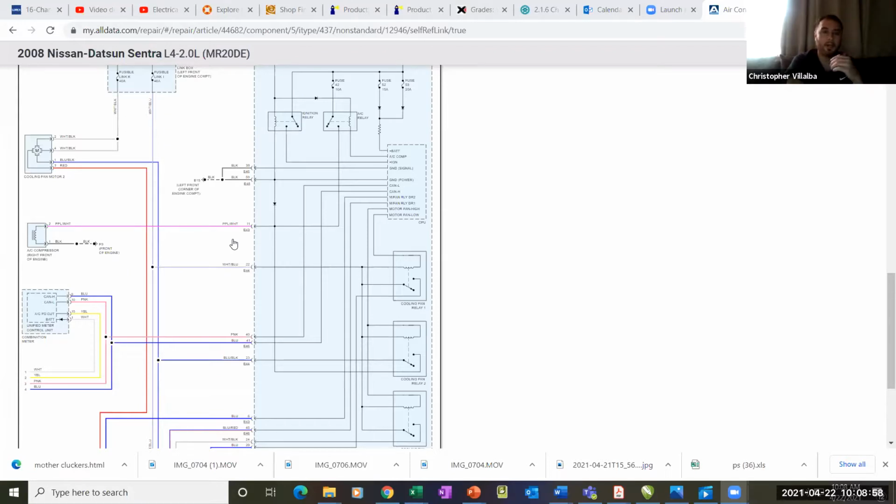I'm like, well, hey, since I knew it just engaged the clutch, we can hook up the old one and do the self-test again with it hooked up, and the clutch didn't go on. So the clutch did fail. The magnet did fail on the other one. We kind of got that from the test, but like I said, the relay obviously has control of that side.